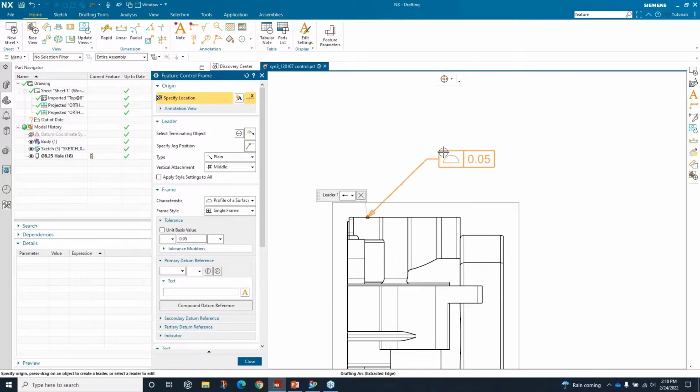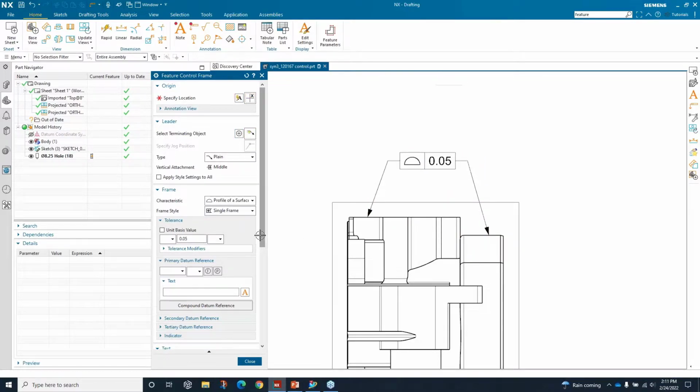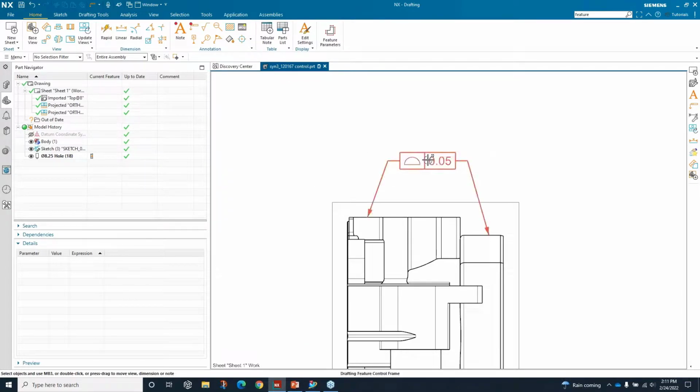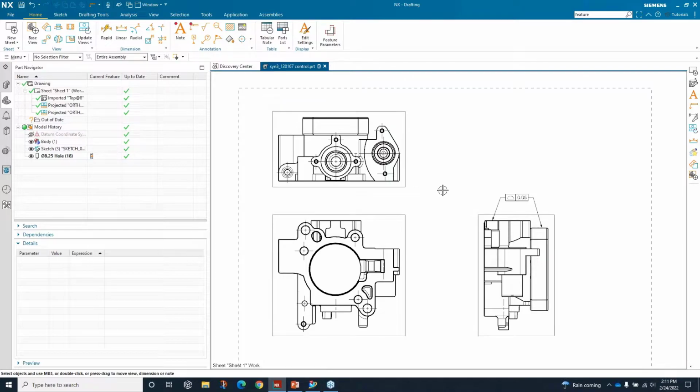So I'm just putting that leader in there as normal. I want to choose another one. So I'll just touch off of another spot. And it's at this point I'm choosing leader 2, right clicking on the stub, reverse. And then I just middle click OK. And there we have it. So pretty neat thing that they have added.